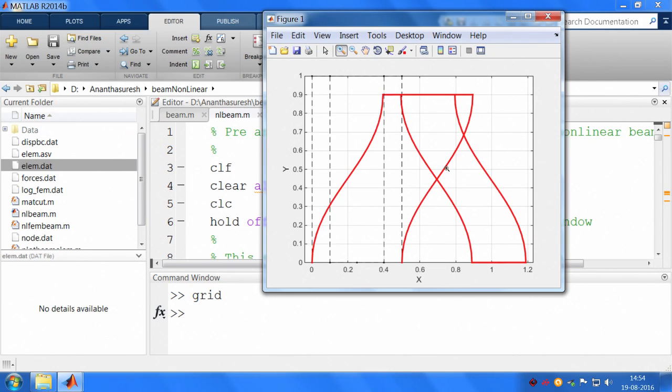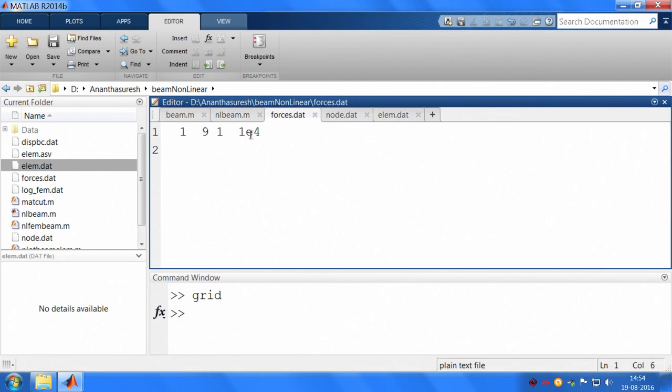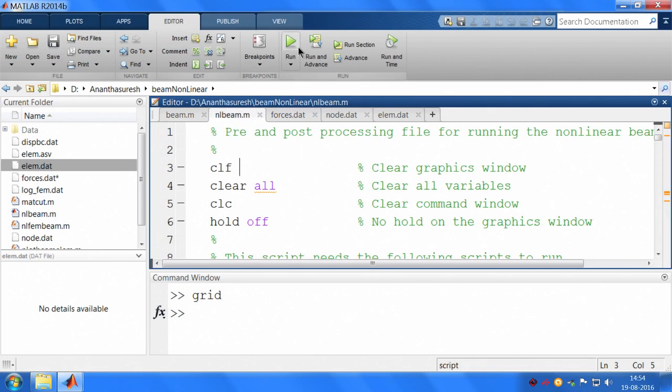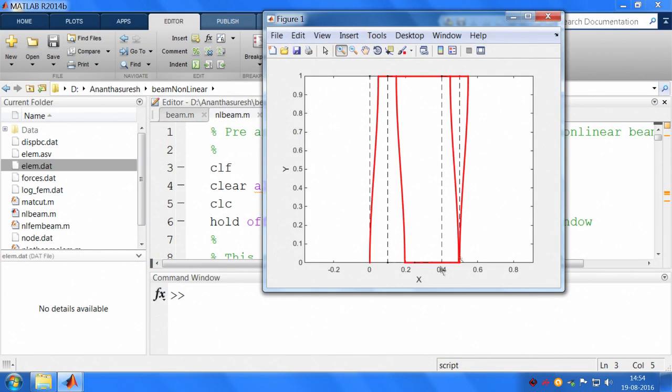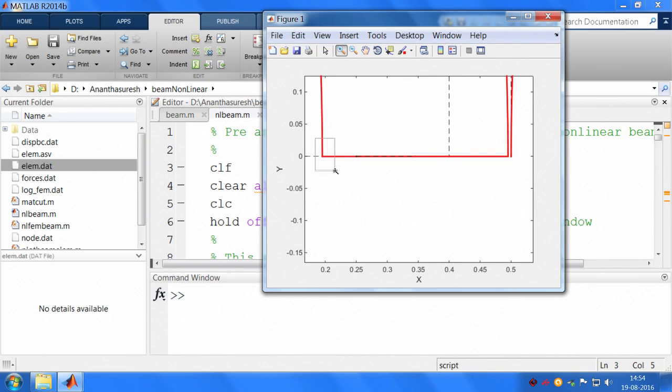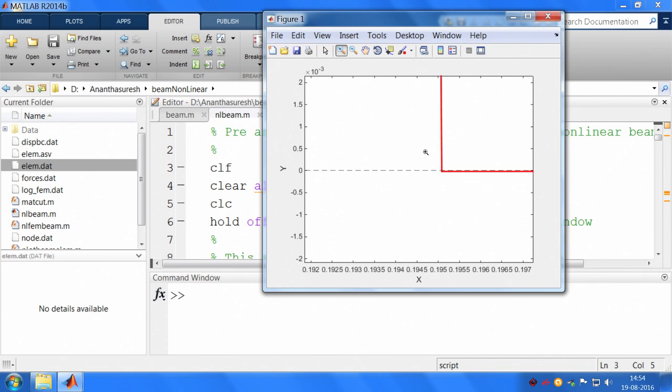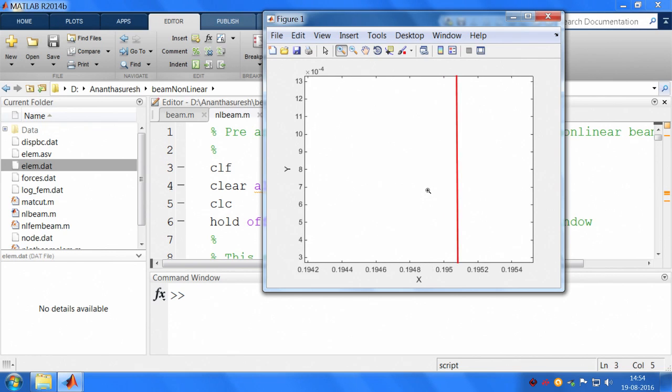If you want to make another modification, which we will discuss after reducing the force, let us not apply so much force. Let me apply 1/10 of that, only 1000 newtons, and then go back here and run it. Now, it is a little bit better. What was the stage here has moved over there. Again, if I zoom in, I might find that it has deflected a little bit. I am really zooming in a lot, then I see that there is a little change. Okay. Over here, I had to zoom in several levels to see that. Otherwise there is not that much of this.